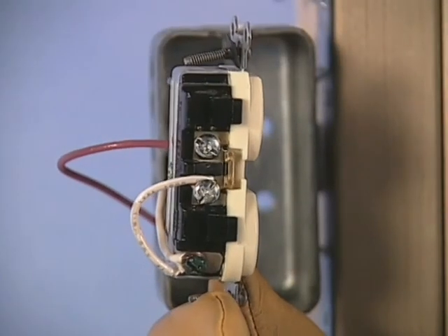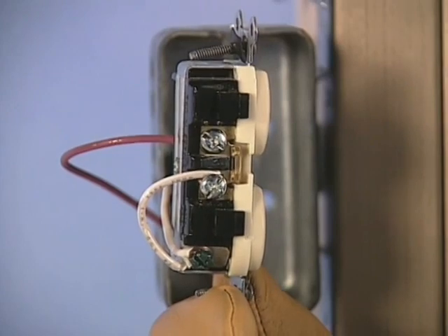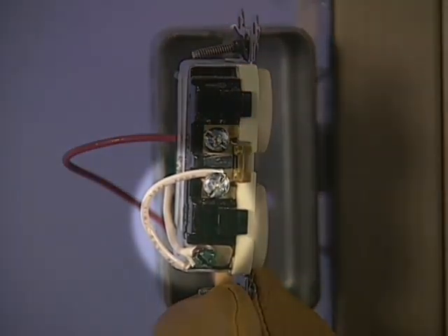And a third situation involves an intentional neutral connection to a grounding conductor. This happens for various reasons. Some electricians may not understand why neutrals must be isolated from ground until reaching the service entrance point. Others may not be familiar with the code. An attitude sometimes expressed is, since neutral is bonded to ground at the service panel, why not here too? Hopefully, this video is explaining why not: fire and shock hazard, as well as interference with electronic equipment, such as computer monitors.